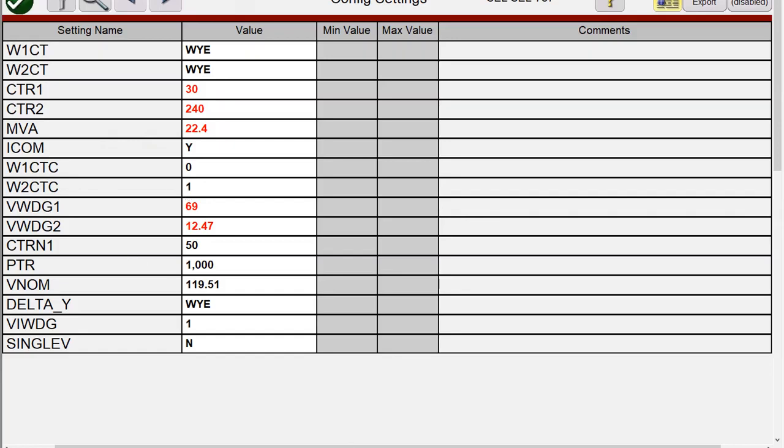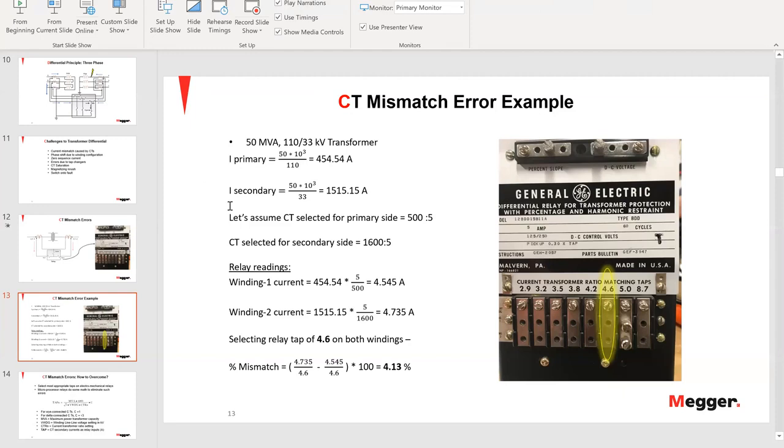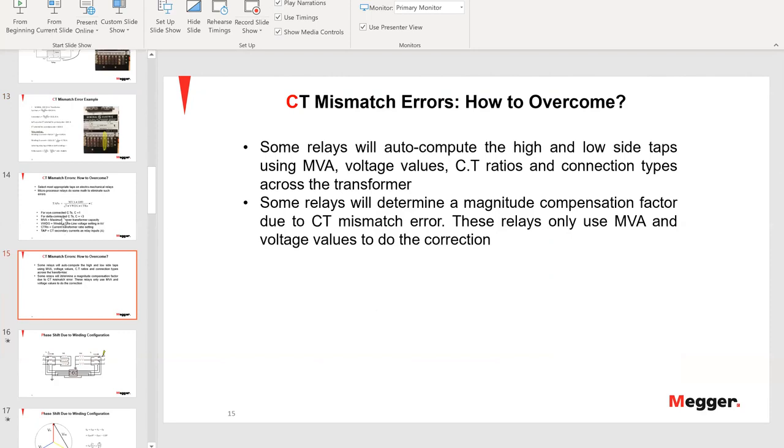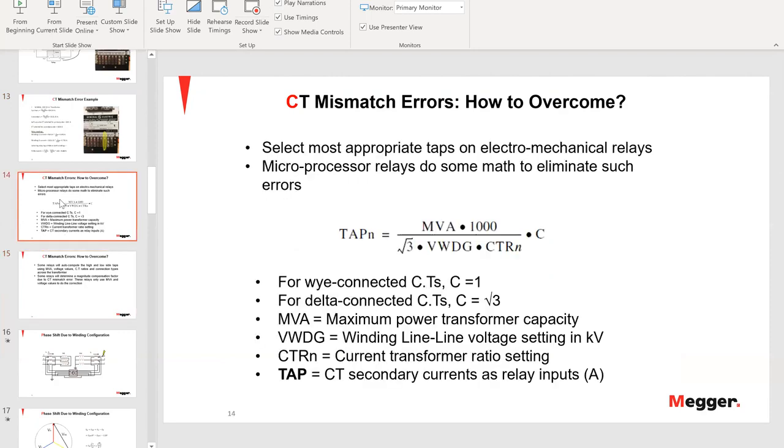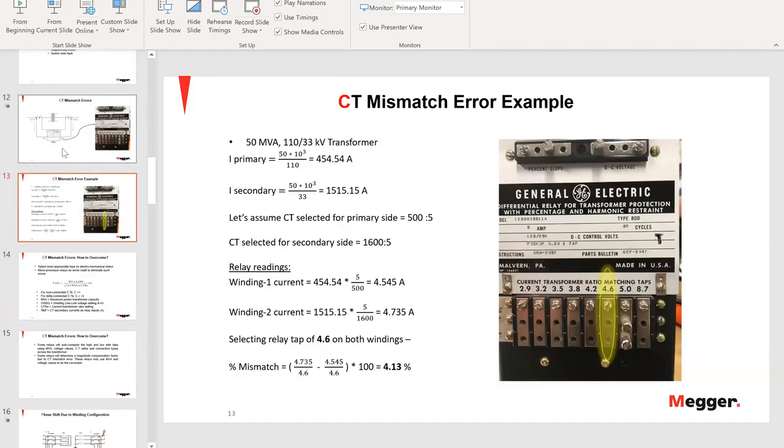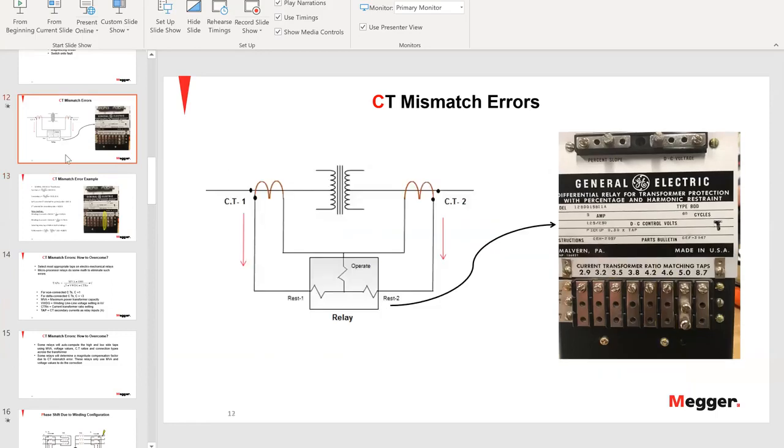All right. Mohit, can I connect my CT in deltas to phase shift compensation? Yeah, absolutely, you can do that. In the olden days, we had electromechanical relays, and there was no way of providing phase compensation using a setting. So in those days, they were using different CT connections to compensate for the phase shift. So yes, you can use different CT connections. Even in numerical relays, they give you options to choose the CT connection as Y or delta. So the answer is yes.